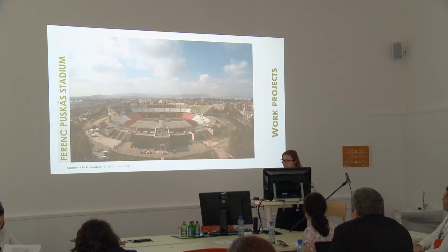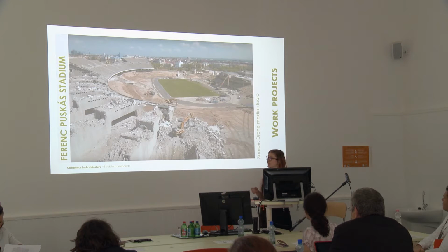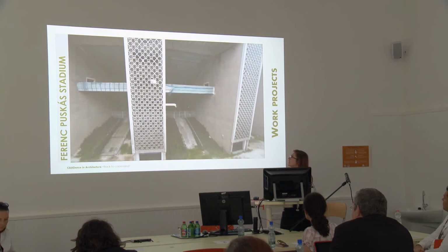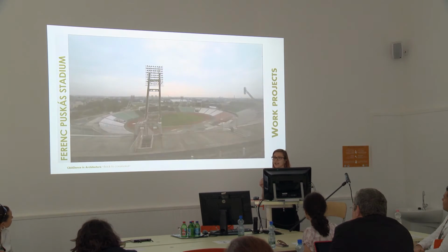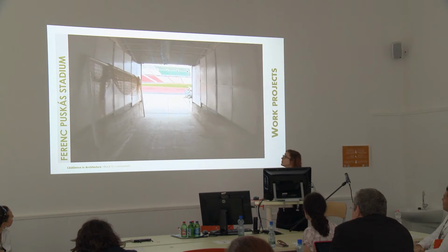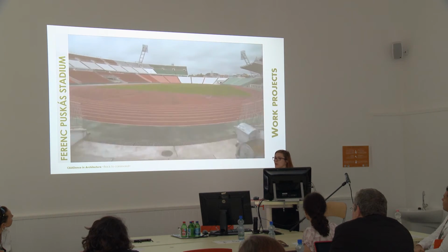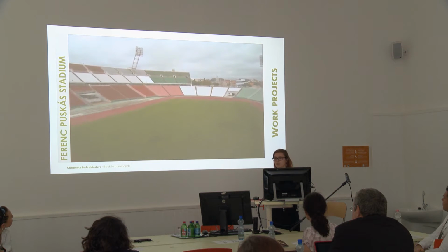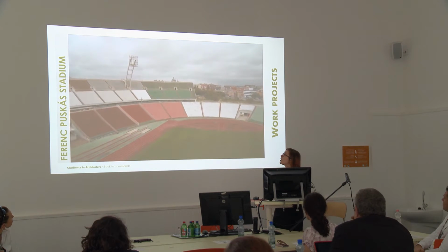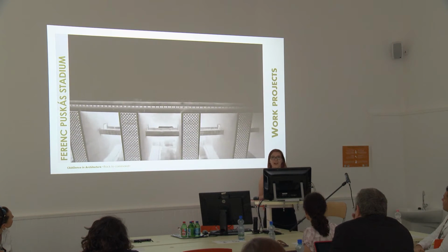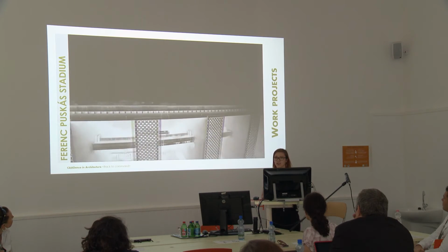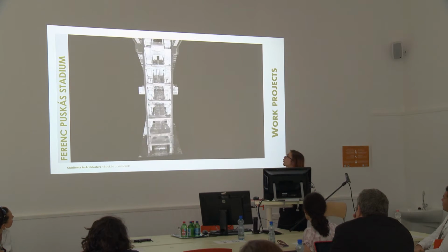in its current state. This 3D digitalization is the last memory of the stadium because the reconstruction started in this year. In combination with the terrestrial laser scanner, UAV technology was also used. The whole building, 72,000 square meters, had been surveyed from 1,400 scan positions for 4 months.